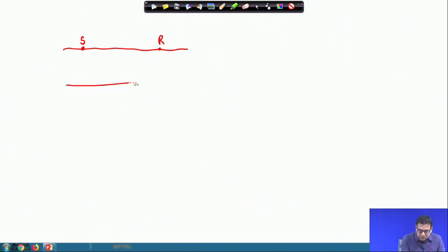and we have another soil layer. So, this is layer 1, this is layer 2, and as I mentioned, we can generate the P wave or S wave depending upon how we are applying the hammer blows. Suppose in all the derivation I am doing, we are generating the P wave. So, we will take the velocity of the P wave, and if I generate it the other way, by putting an iron block and applying the hammer blow on the side of the block, then that will generate the S wave.